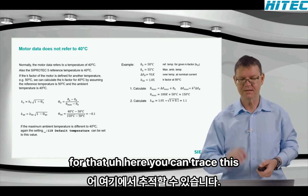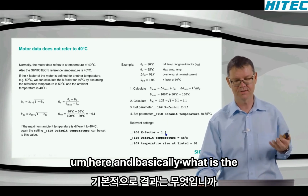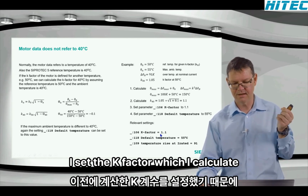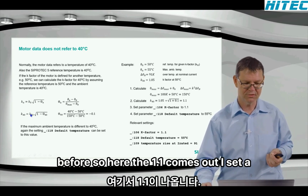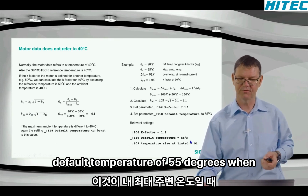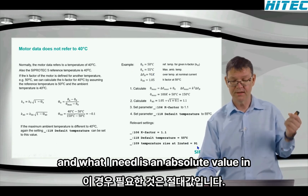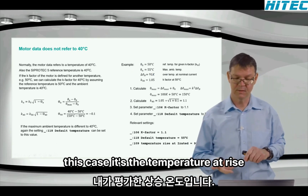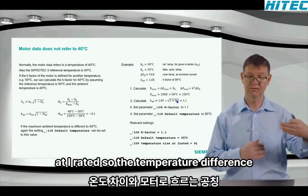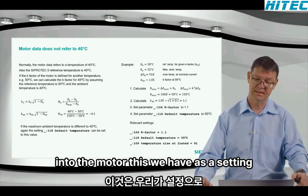Here you can trace this calculation here. And basically, what is the outcoming? I have three relevant settings. I set the K factor, which I calculate before. So here the 1.1 comes out. I set a default temperature of 55 degrees when this is my maximum ambient temperature. And what I need is an absolute value. In this case, it's the temperature rise at I rated. So the temperature difference when you have a nominal current flowing into the motor. This we have as a setting.